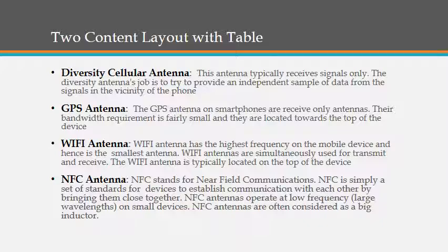If the magnetic fields from one inductor pass near another inductor, an induced current will exist within the second inductor. This is contactless energy transfer, exactly what NFC requires. A good NFC antenna is as large as a wrapped coil of wire. Recall that a loop of wire around the material gives a strong magnetic field within the loop, so the more turns you have, the more inductance you create, which is better for the NFC antenna.